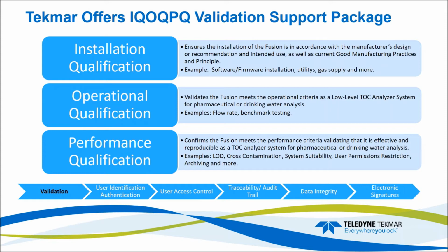And then you have your performance qualification, which confirms the Fusion meets the performance criteria, validating that it is effective and reproducible as a TOC analyzer system for pharmaceutical or drinking water analysis. Examples of that are a limit of detection study, carryover or cross-contamination, system suitability, user permissions, restrictions, data archiving, and more.